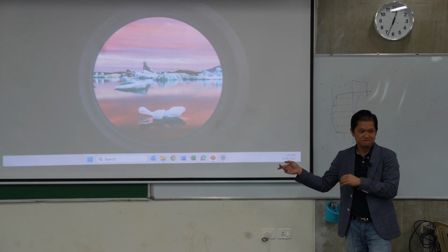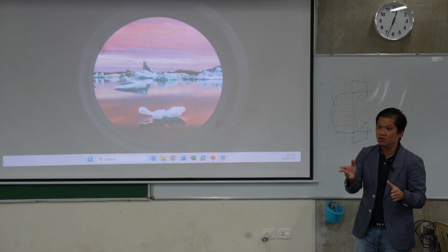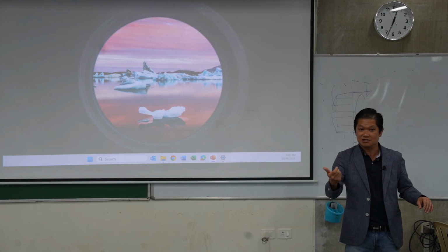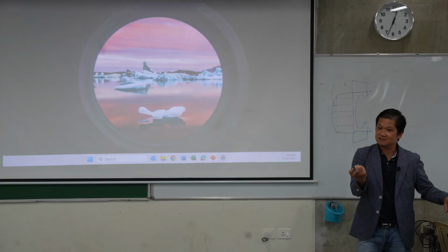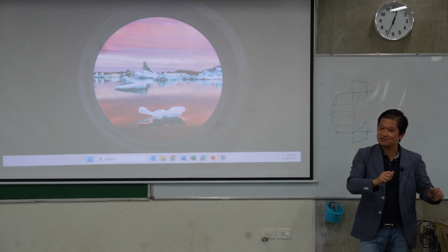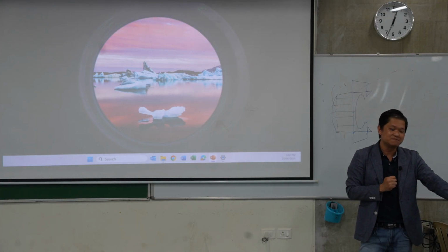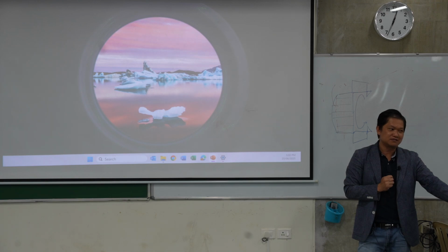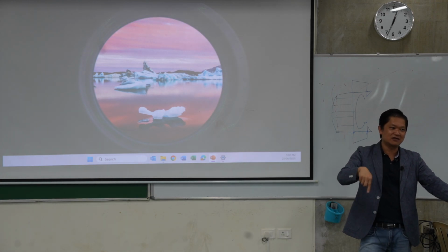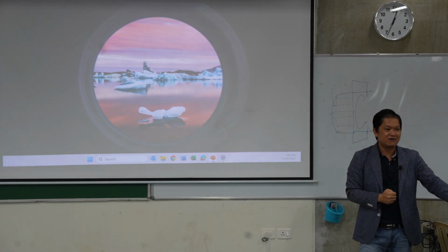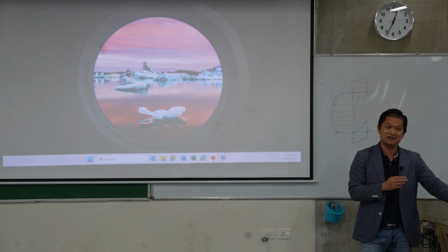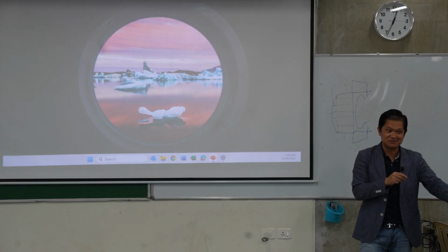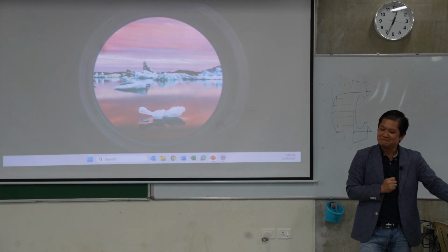Particularly for thin-wall sections, not like hot-rolled, right? With hot-rolled you can go up to 3 because of the tension field action, and the flange is good enough to hold that, so it creates a large tension. But for cold-formed steel, because of the nature of one section, one thickness, it is going to fail in local buckling, unfortunately. So that is how we're doing. So that's a very good question. I mean that you got it very deeply, but that's what we do.